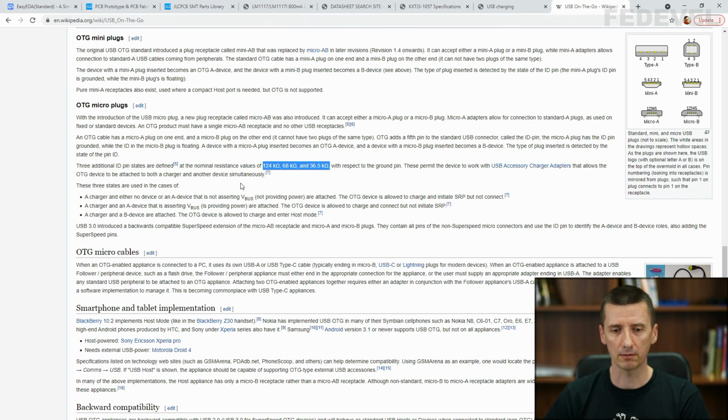And the very safe way we can connect this pin is to just use a 0 ohm resistor connected to ground. And in case you need to experiment with this pin, then just unfit the 0 ohm resistor, leave it unfitted, or you can put there resistors with different values.